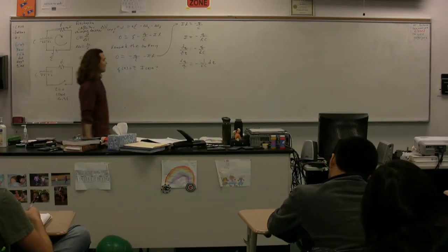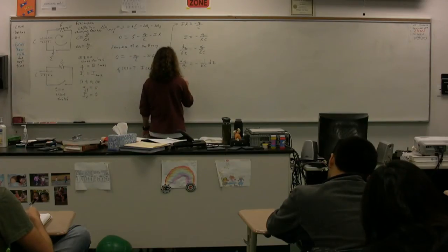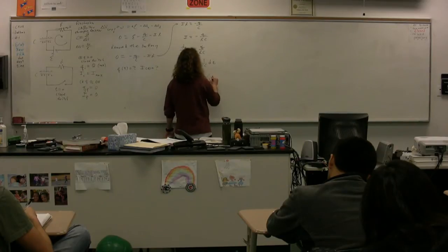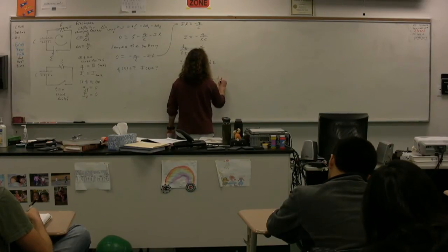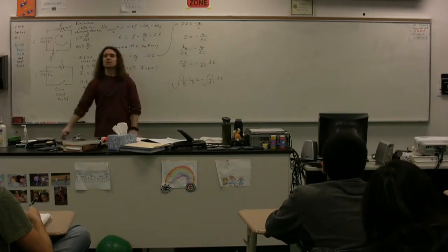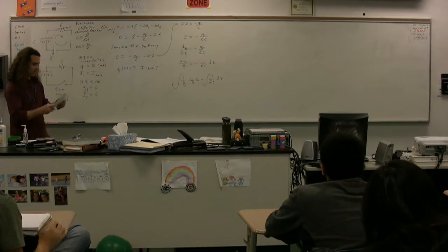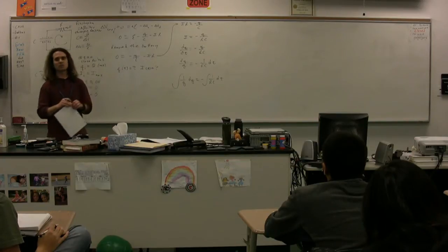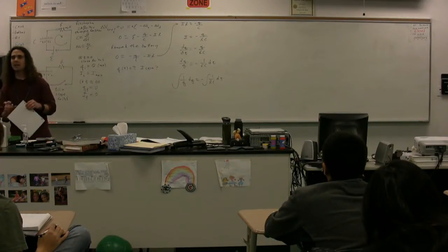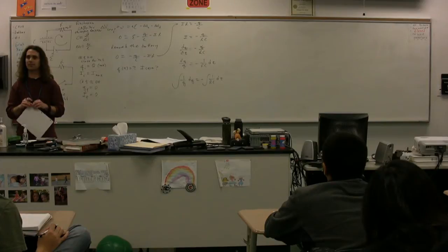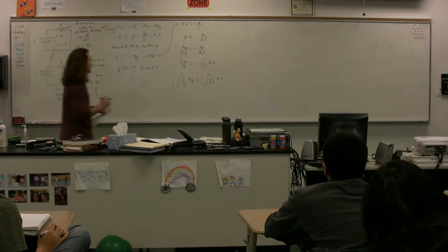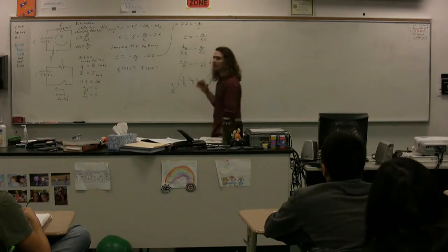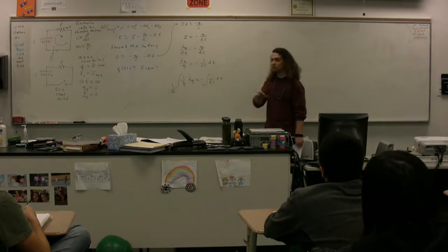We take the integral now of both sides. We have the integral of 1 over q with respect to charge is equal to the negative of the integral of 1 over RC dt. Limits. What are the limits on, for example, q? Where does it start and where does it end? Big Q starts with big Q, and is 0. Right, but remember, we're ending at some time t that is in between 0 and infinity.